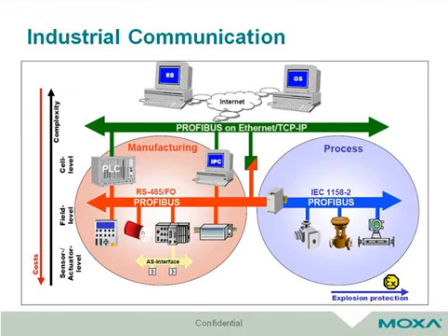At the field level, the distributed peripherals such as I/O devices or drives communicate with the automation systems via an efficient real-time communication system. PROFIBUS meets these requirements and offers a transparent solution for manufacturing as well as for process automation. At cell level, the programmable controllers such as PLC and IPC communicate with each other.